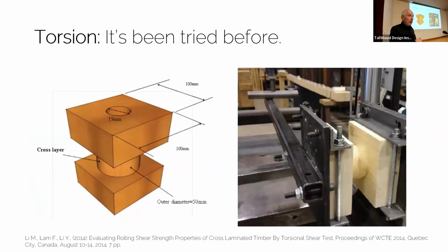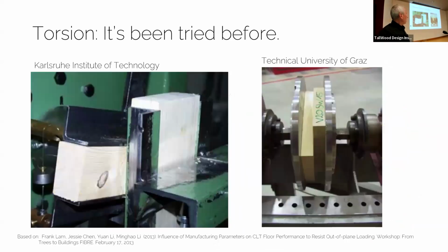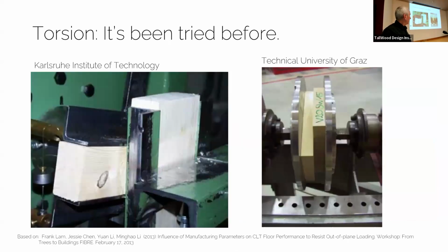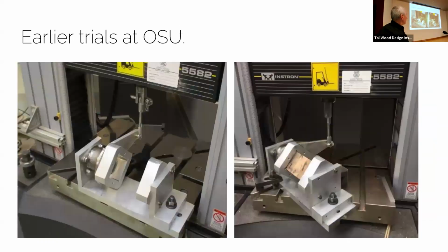That's easy. People are trying to replicate it with wood in now transverse direction to replicate shear in wood, and it's rather a nightmare. I mean, you could do it, but just the level of machining in here and the outcomes that you have are not really conducive for large scale testing, and particularly not for creep. Similar tests are being done on the adhesive bonds. It's not quite the same thing.